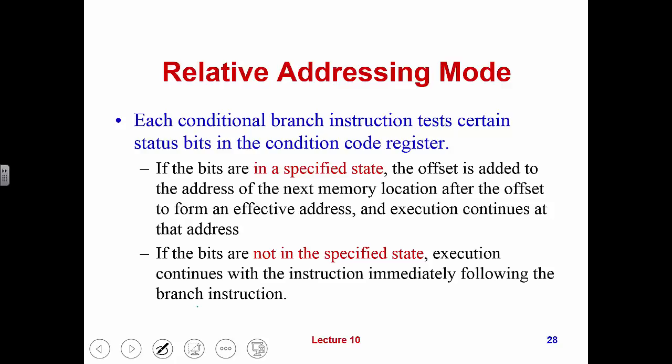In general, if you recall what we learned about the branch instructions, we mentioned that a branch is taken based on a test result. The test result is in general based on testing the condition code register values, the CCRs. Most of the time when we branch, we test whether we meet a particular condition or not, based on the computation result, by testing some values of the condition code register flags.